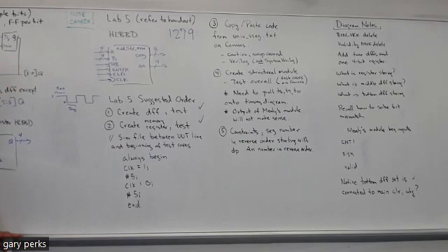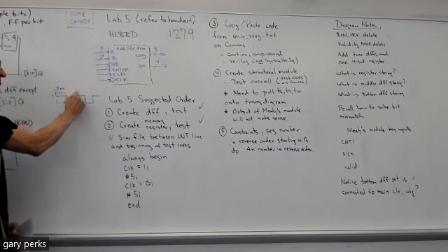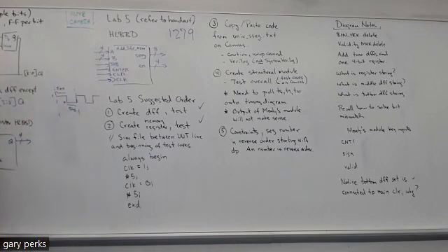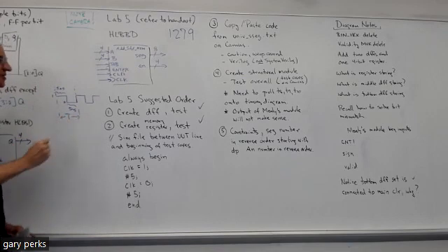that we call a clock. Now, what is the period of something like this? What is the period of this square wave that's high for 5 nanoseconds, and low for 5 nanoseconds, and high for 5, low for 5, and it just keeps doing the same thing? What's the period of that? 10. Yeah, just 10, right? You all learned about period of a waveform in physics, and I'm sure you've seen it in an EE class at some point. You've had an EE lab, right? This is the period, right? It's just the time it takes for a waveform to repeat.